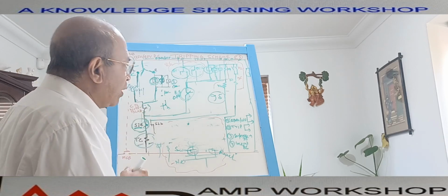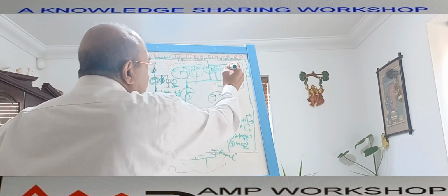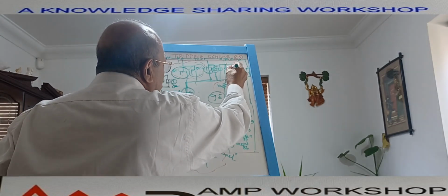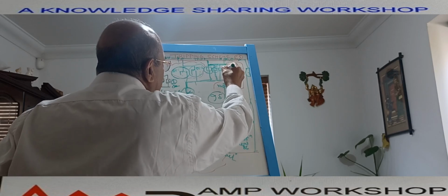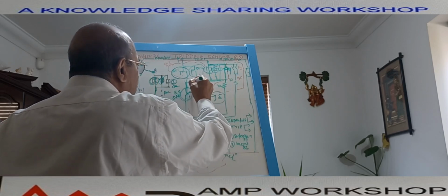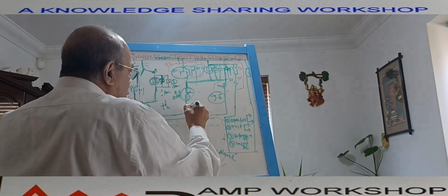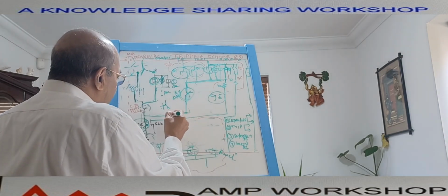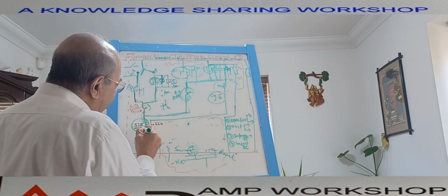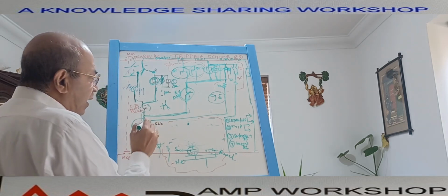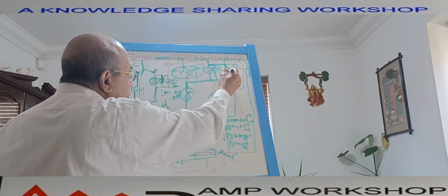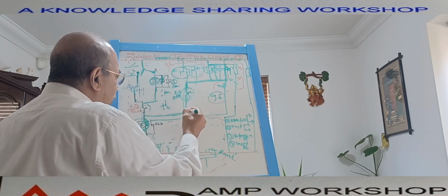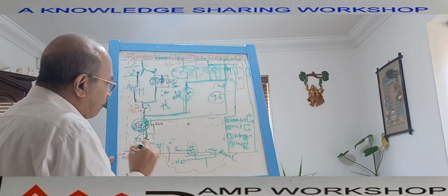So how is that working? This is the first trip coil K1. This is the first coil K1, which is connected to the positive side, and it is going through this. You see here, it is going through the arc switch interlock, and then it is coming over here, and it is a breaker NO contact. So when the breaker is closed, this contact is NC. So through this path, the K1 coil is getting energized, and through this power is going.